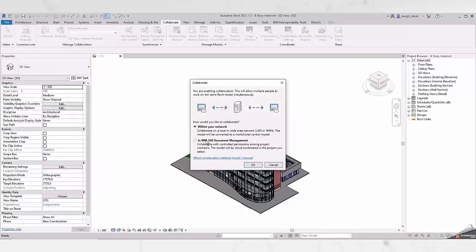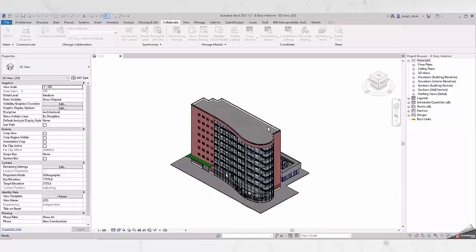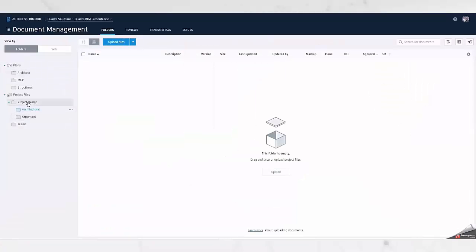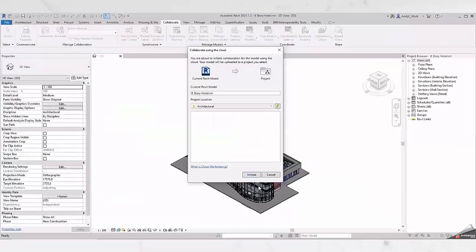I start coordination as I would in Revit and go to BIM 360. This uses my desktop connector to connect to the shared data set, and you can see that the population of the file structure is there waiting for me to use, because my desktop connector brings me that representation in here, which is of my project files location. We'll discuss project files and other things later.